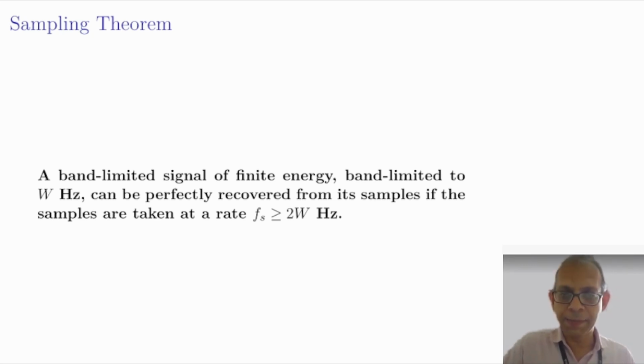Now, for the time gap between two successive samples, the channel remains free and unutilized, and that time can be utilized for transmitting the samples of other signals. This idea is called time division multiplexing. Let us try to understand it.